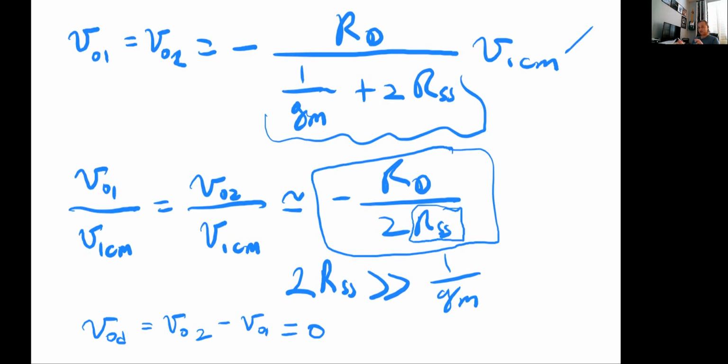They are physically two different dynamic loads. And the idea is that we need to match them because we do want them to be the same to help with our common mode rejection and the whole idea that the pair is matched. But in reality, that's not the case. So I need to investigate what are the effects of not being able to match the RDs.